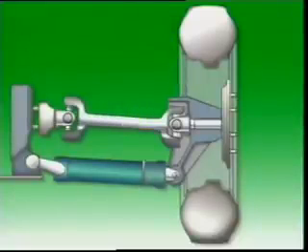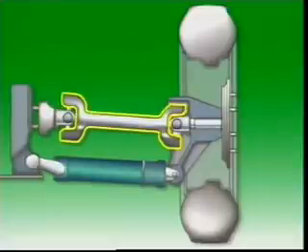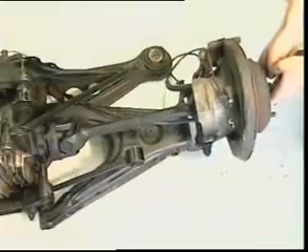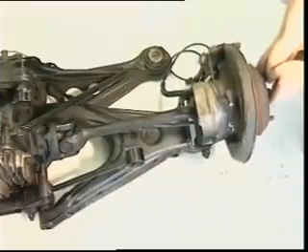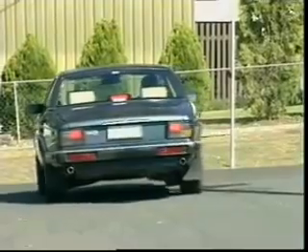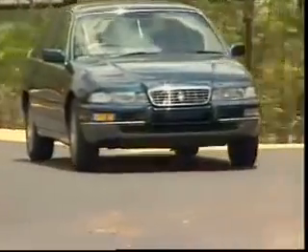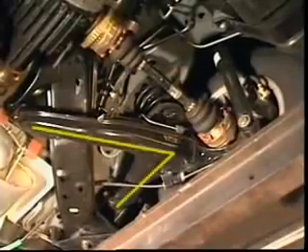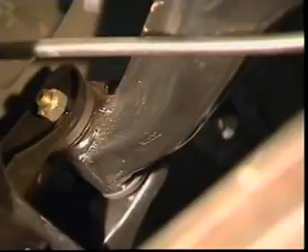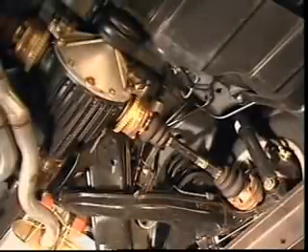However, the drive shaft itself can be used as the upper link of the suspension, providing the pivot point. The spline section is unnecessary, and the shaft can be made as one piece. As with the front suspension, the lower link has widely spaced pivots to provide stability, and the unequal length links maintain the track nearly constant, although with deflection, some camber change does occur. In some designs, the wheel units are located at the outer ends of semi-trailing arms. The arms are attached to their cross-member pivot points by rubber bushes, and constant velocity joints are used at each end of the external drive shafts.